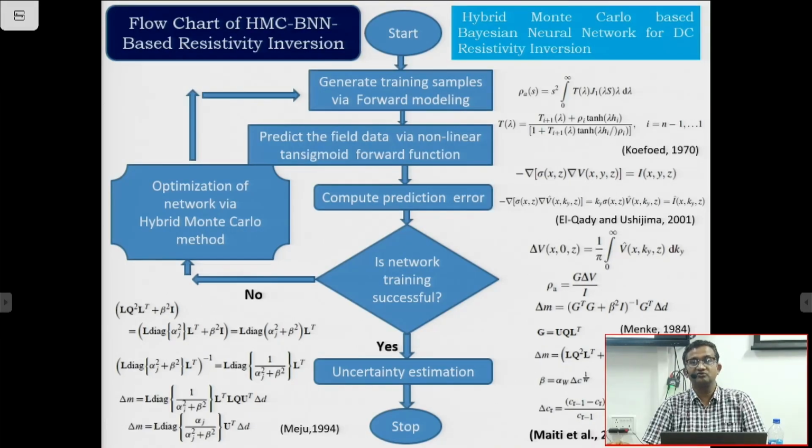If you want to know the vertical variations of your resistivity, then Schlumberger will be the better one compared to Wenner. Wenner captures lateral variations of resistivity better. Now, if you want to capture the lateral as well as the longitudinal, then there is a combination called Wenner-Schlumberger.